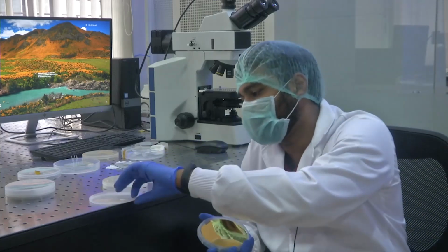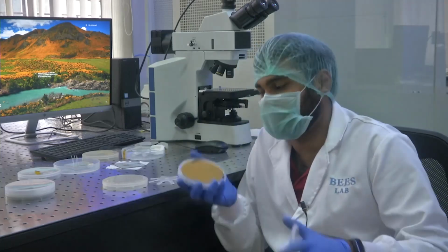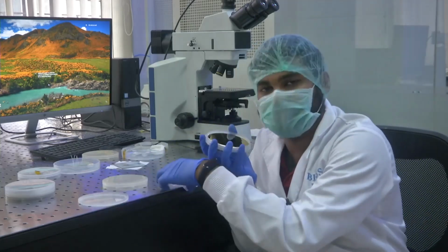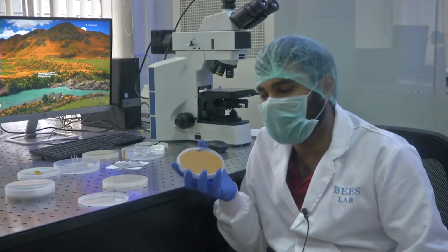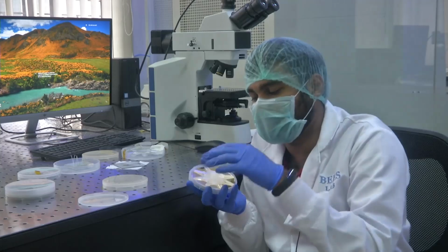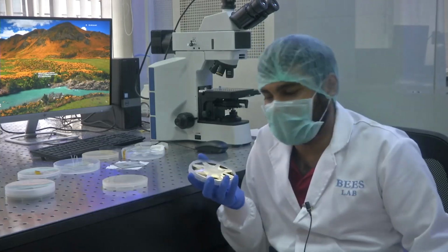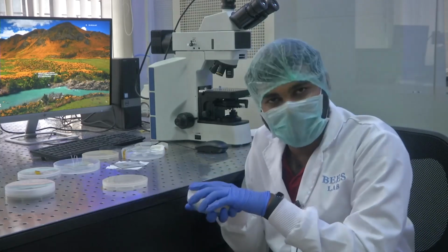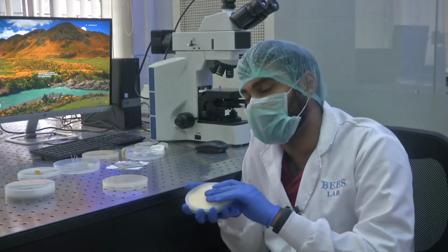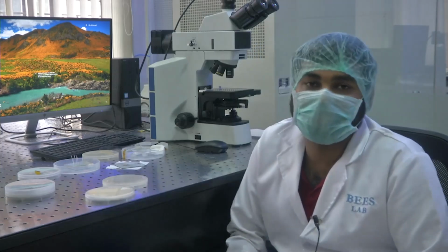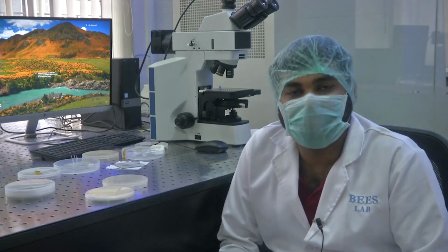Now the sensor that I am going to show you, we have fabricated using platinum. I am showing you gold because right now this is available to us to show to you. The sensors can be fabricated on gold also. Why we choose different materials depends on the design constraints again. Gold has very good conductivity, and platinum has good conductivity too, but the thermal coefficient and conduction coefficient will be different between platinum and gold.